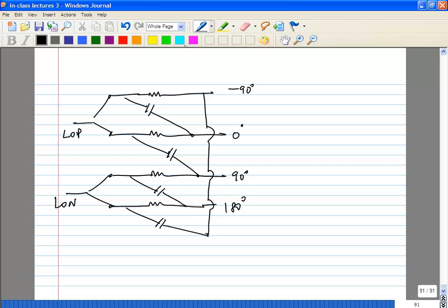If you look at the two phase signal coming in, you'd have something like this. So the things to remember: if you want to drive these kind of resistive loads, you need power, which means good buffering. Otherwise the VCO Q will go down, right?